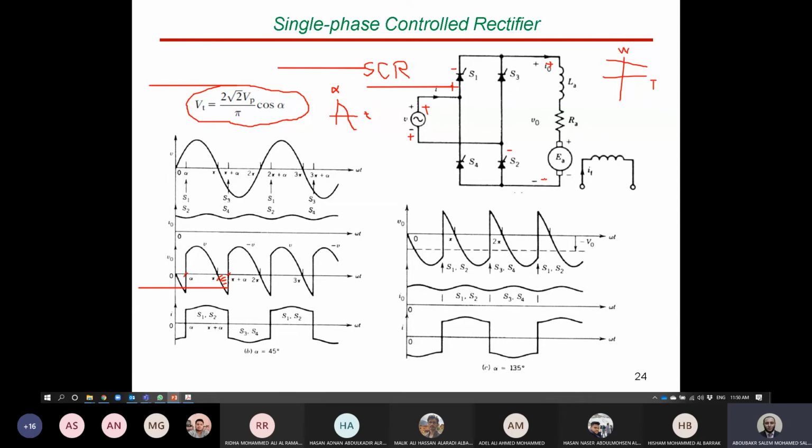So if the voltage is reversed and the current stays in the same direction, this can work now in regenerative braking. Is it right? Because the power will be negative, which means the power will be returned to the supply. So it's not now a reverse motor operation. We cannot decide based on voltage only in this circuit. But later, inshallah, we will discuss some circuits that can be used to reverse the motor direction, or to operate the DC motor in the 4 quadrants.